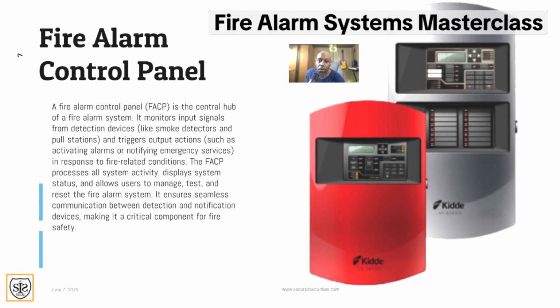So if the alarm goes off on, let's say, the 3rd floor, you will map that alarm signal to the LED with that label, so that way the person downstairs watching the control panel will know that the alarm is on the 3rd floor. It would also indicate it on the main control panel as well to give you that display, especially with the addressable systems.